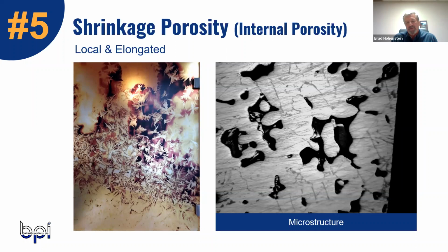It'll happen a lot towards the gate, towards the gating, but it also happens between thick and thin surfaces, thick and thin walls of the casting. You may see it not too far from the riser, where the riser just didn't have enough quite to get it all the way there. And you'll see an area that may show sponge shrinkage like that.